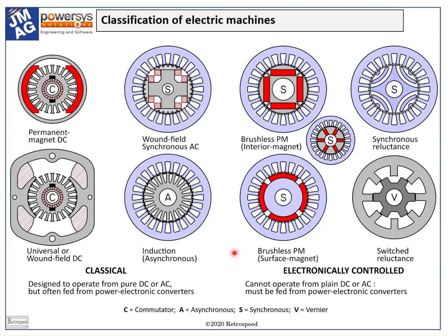These motors are extremely common. They're used in electric and hybrid vehicle traction and in hundreds of tools and appliances where controlled motion and high efficiency are required. They're usually fed from current-regulated pulse-width modulated transistor inverters. Although we will concentrate on the surface magnet motor, the same principles also apply to the IPM, or interior permanent magnet motor. The surface magnet motor is simpler because its rotor is rotationally symmetrical.